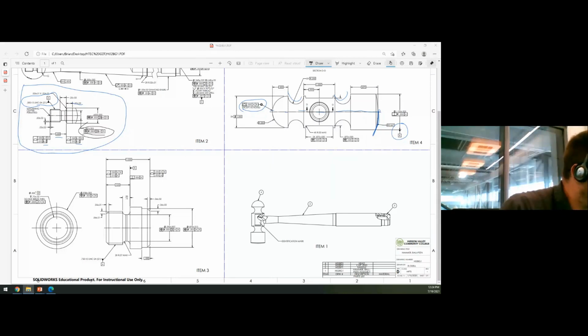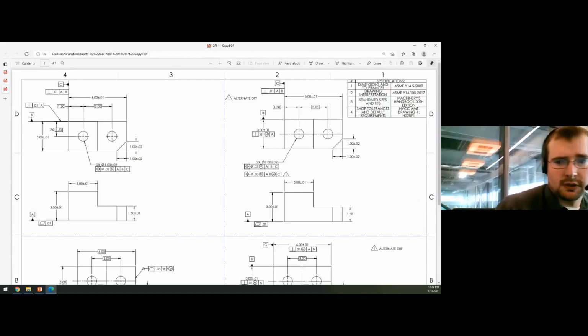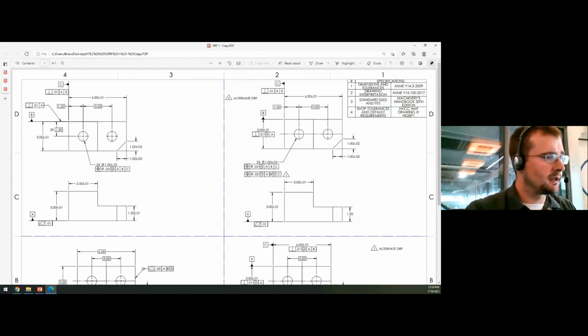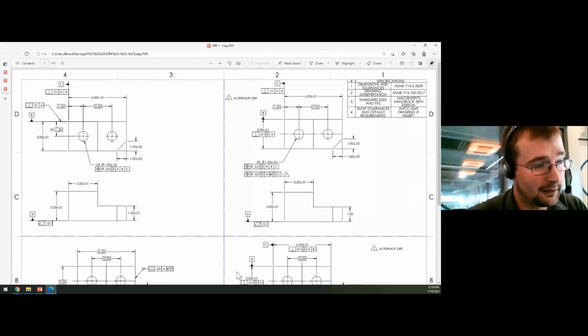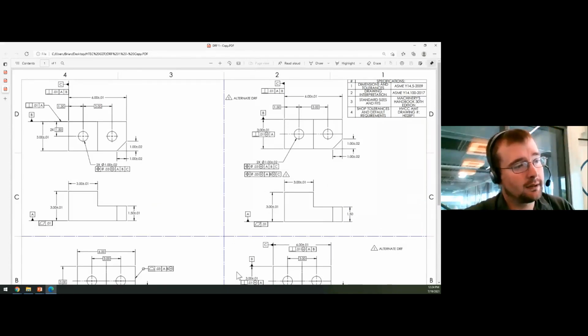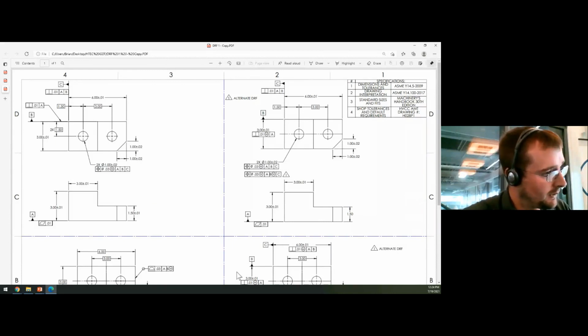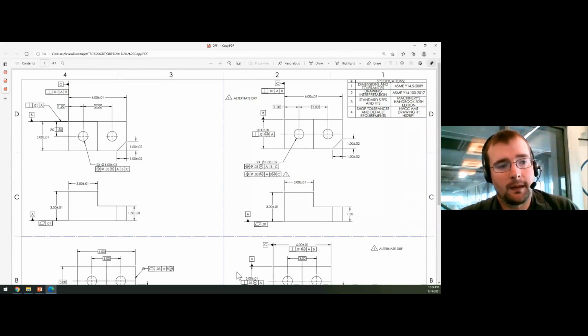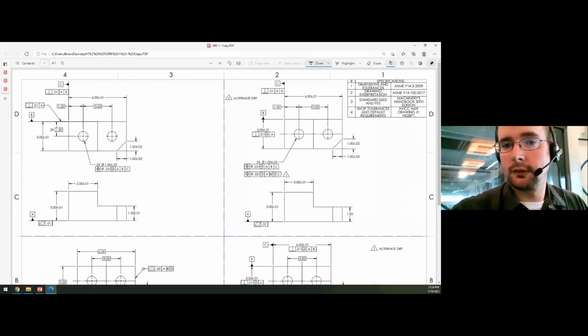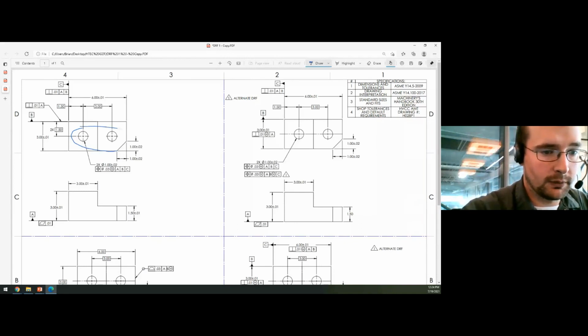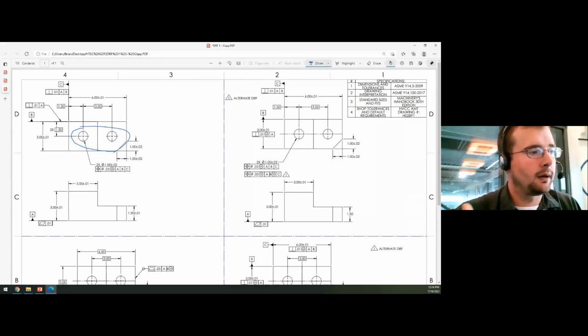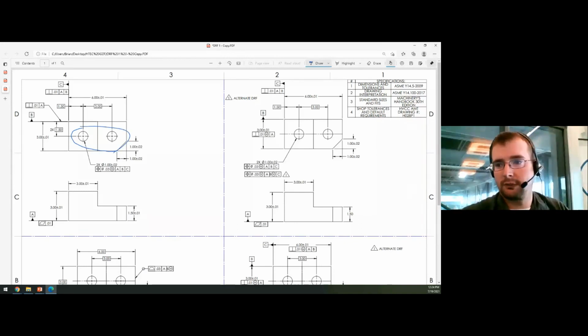And I think that's the last one I want to cover before we finish the slideshow. This is one of my favorite drawings that Dean Odell did. This drawing is to help not only his class, but all the shop classes understand datum reference frames, because in our opinion, the datum reference frame, from a machining standpoint, is how to fixture it. It's how to fixture it between manufacturing and assembly. It's how it's supposed to be held, where these holes need to exist in the assembly. So he has 4 different parts, 4 different datum reference schemes.